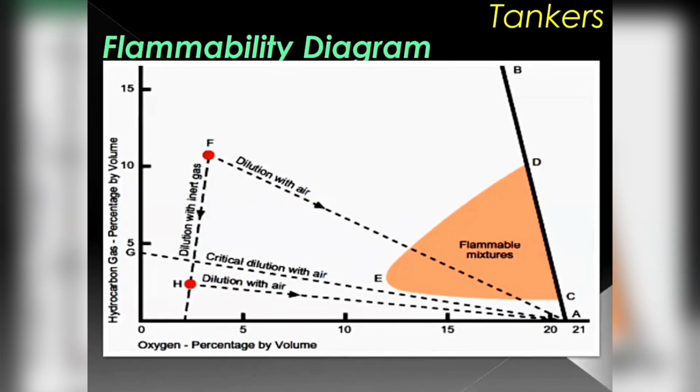When the LEL comes to 33% or 50%, you stop and vent it out. Those procedures can be done on non-volatile cargoes where there is no inert gas. When there is no inert gas, you have no choice; you have to follow this. But for volatile cargoes, you cannot take these chances. Okay? Yes, sir. So this is the upper flammable limit and the lower flammable limit.